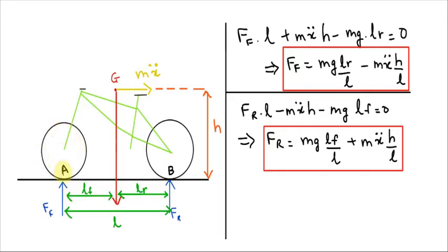When we do a wheelie, there is no contact between the front wheel and the ground surface. Hence, we can say that in a wheelie, no force is exerted by the front wheel on the ground surface. So that means we need this value of Ff to be less, or maybe zero. But let's say we are trying to assess the chances of doing a wheelie. We can say that the lesser the value of Ff, the more the chances of a wheelie.